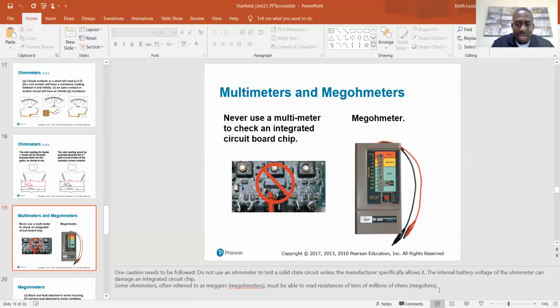That is not something that I have ever attempted in the field. A bad board is a bad board. I change out the whole board. I don't get into electronics to that extent. That is not a typical HVAC task. We'll diagnose the board and just swap out the whole board.